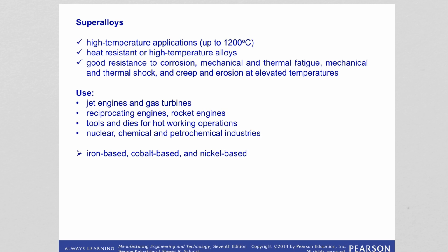Thermal shock is when we suddenly change the temperature of a material, because inside the material there will be differences of thermal expansion that might create stress in the material, and those stresses can crack the material. Therefore, thermal shock resistance is the ability of the material to withstand sudden temperature changes.